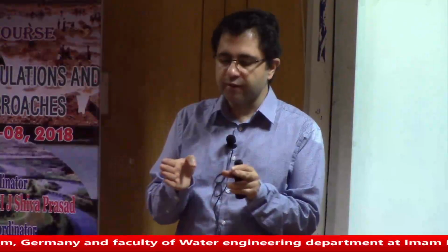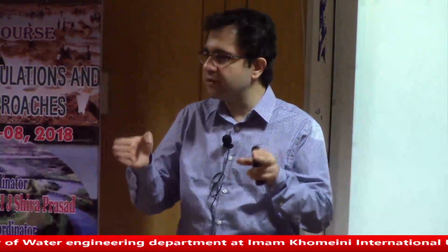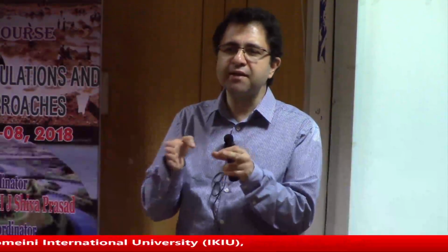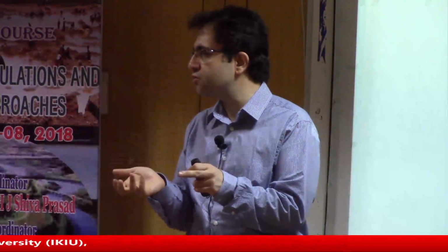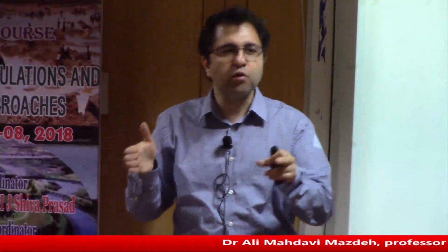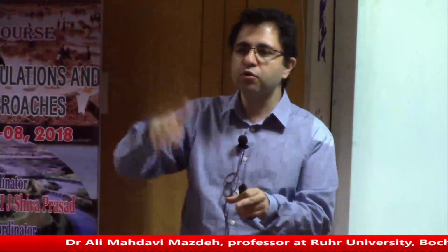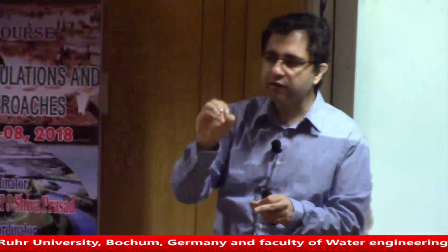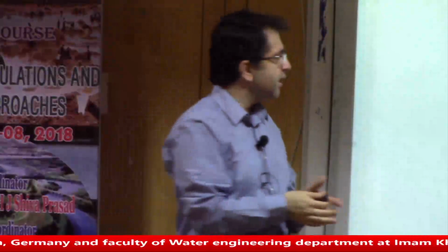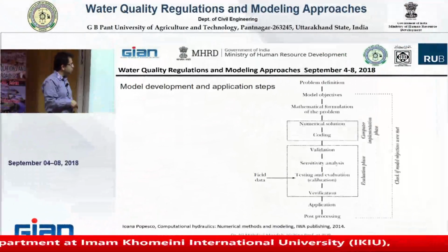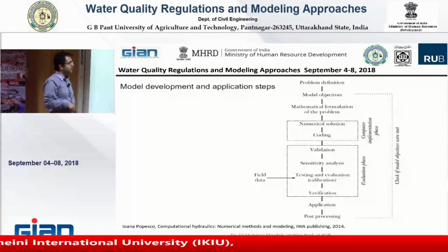But if you start to make it smaller, then you reach the point that when you make it smaller, the result doesn't change so much. So this is the optimized grid. You don't need to make it smaller. When you make it smaller, the time will increase. So you should find the optimized grid, and after that, you are going to do testing, evaluation and calibration.